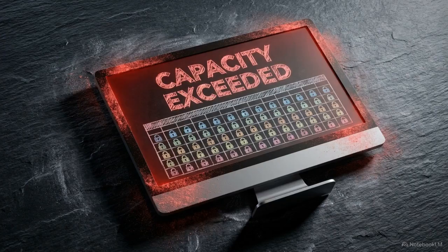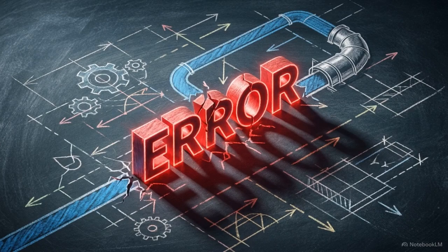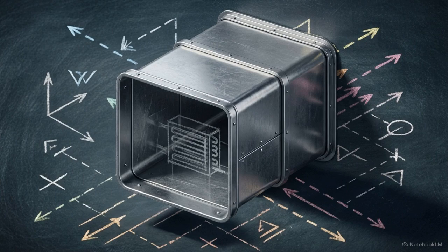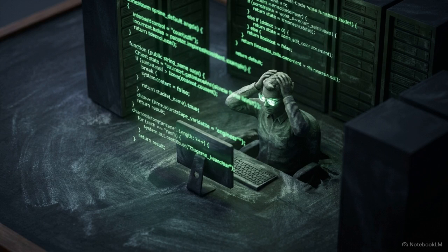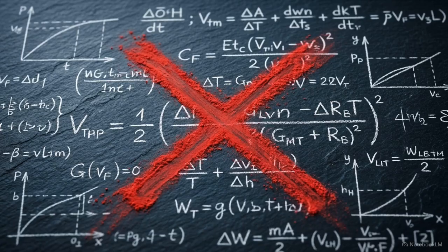Because the space loads were pre-calculated and fixed in step 1, the program can only log the deficit and report an unmet load. This decoupling prevents engineers from analyzing how varying supply water temperatures from an overloaded plant directly degrade the capacity of secondary coils. Furthermore, these sequential programs rely on rigidly predefined system templates. Modifying a system architecture often requires altering and recompiling the underlying source code. By decoupling the load from the equipment, sequential models ignore the basic physics of thermal interaction during moments of peak system stress.